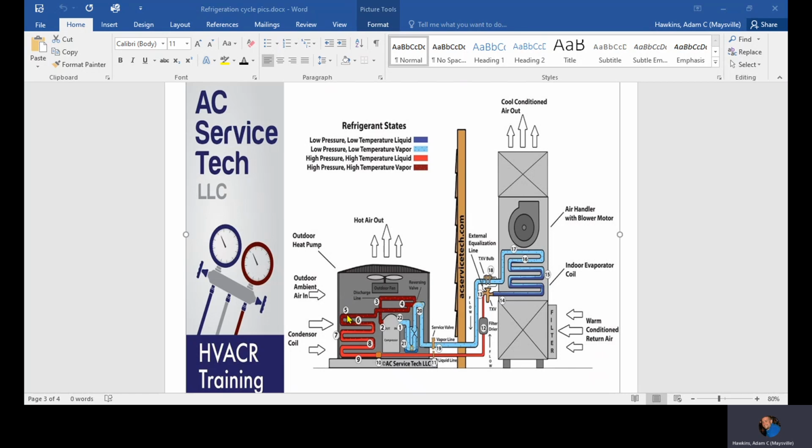So I increase the temperature of this coil, knowing that even if it's 100 degrees outside, that's fine because my coil will be warmer. You heard me earlier say indoor minus 30, outdoor plus 20. That's just a rule of thumb, but it gets you an idea of how this thing's working. So the inside has to be colder. The refrigerant temperature has to be 30, 35 degrees colder. The outdoor refrigerant temp has to be around 20 degrees warmer.